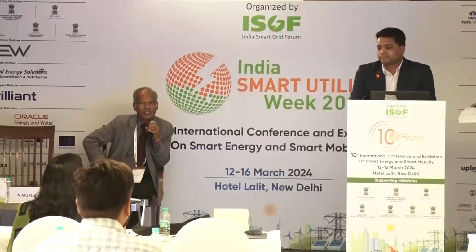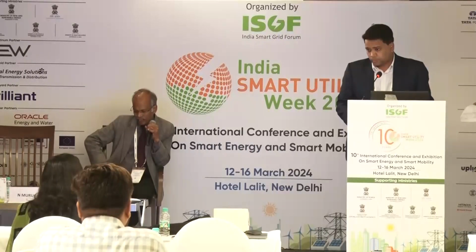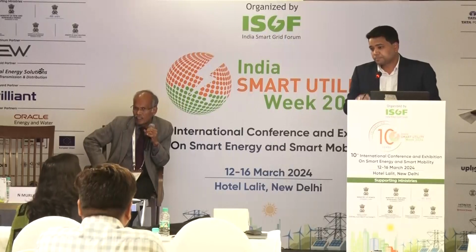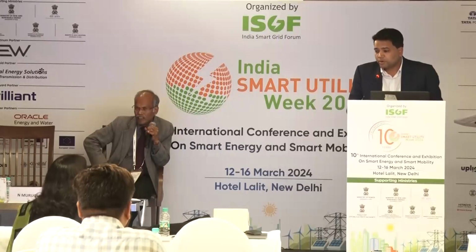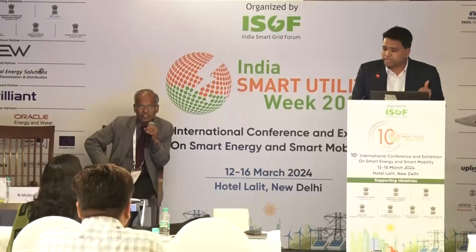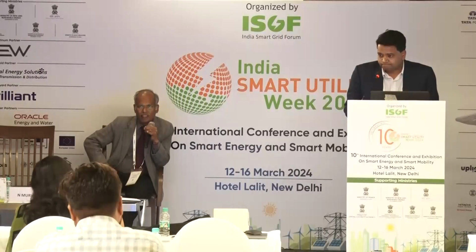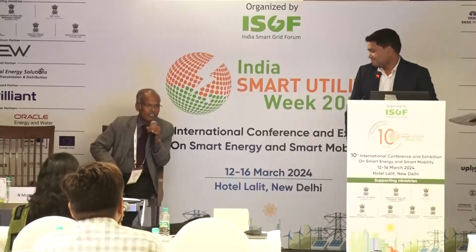Thank you. And only one more point. We know the GWP value for SF6 is around 20,000 plus, close to 25,000, around 22,800. So now, with this alternative gas, what is the GWP value? It will be less than 1,000. Oh, yes, that's very good. For the eco gas mixture, it is less than 1,000. Good. Thank you. It's quite an interesting topic.